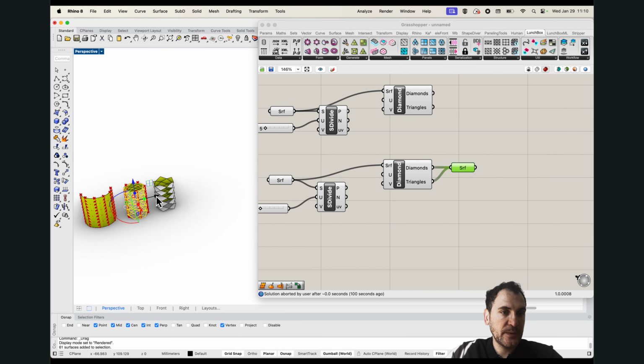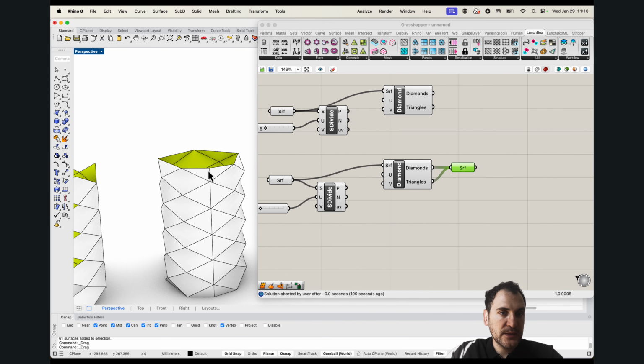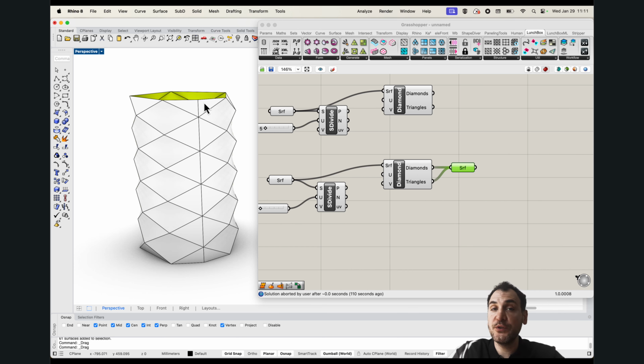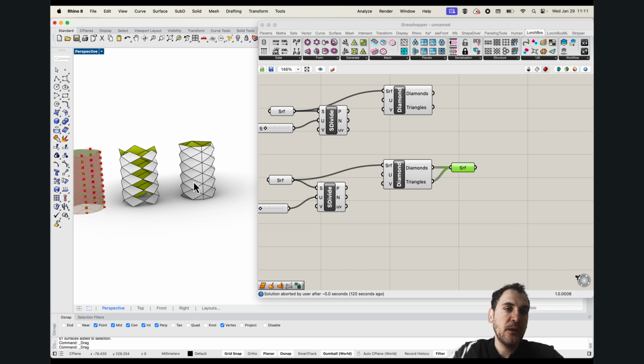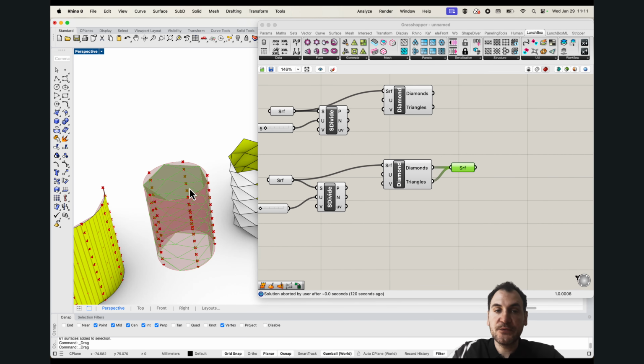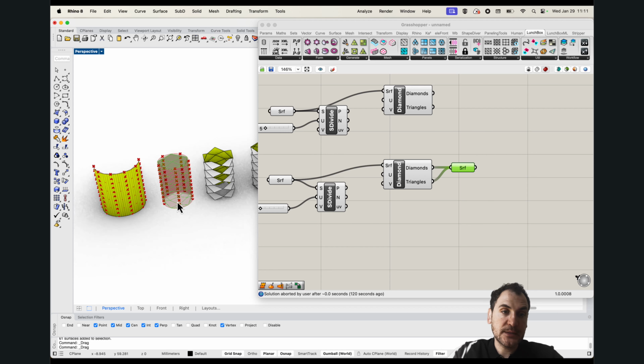If you also bake the triangles, you can see that this is the edge of the surface, and that edge we get for all lofts in 3D modeling. Essentially that's the start of the surface, and it wraps itself around, and it's a point of discontinuity, right? So Lunchbox is still treating the surface as if it's an open surface.